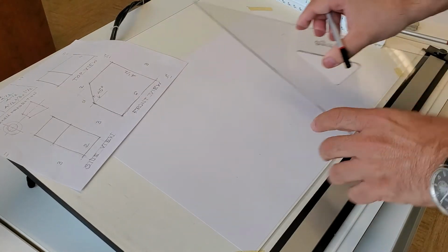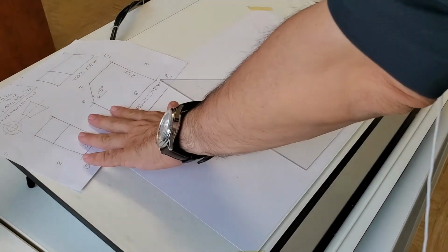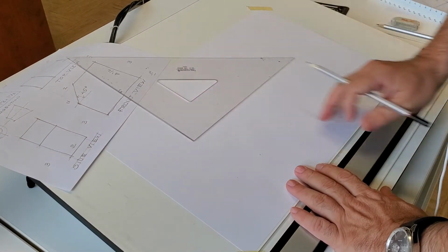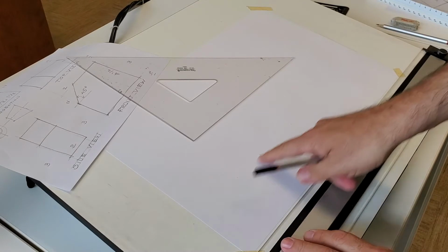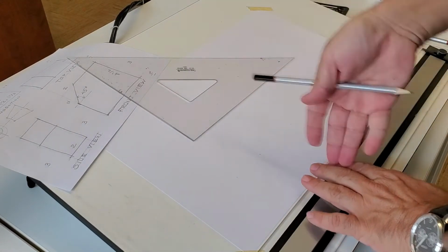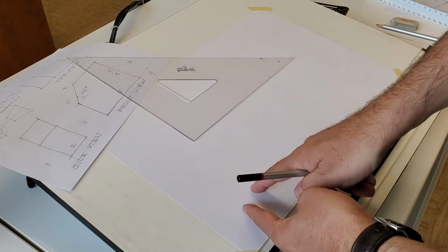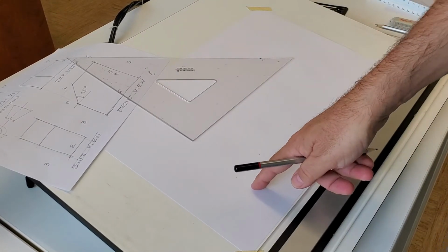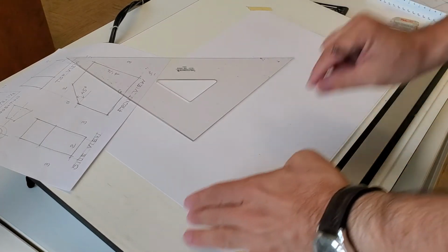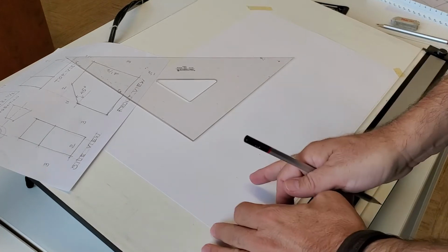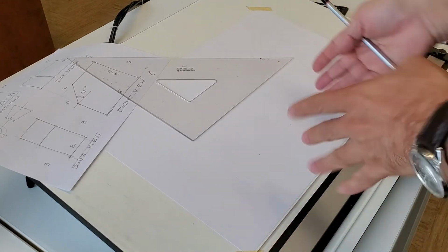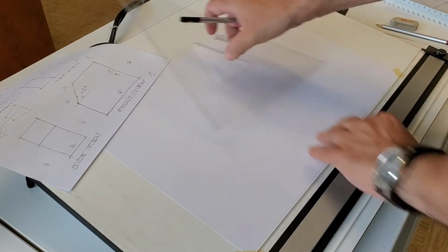Okay, so one thing is important, that you always work in series. It means that when you are doing a task, finish all of it as much as you can. Here I put all the dimensions, I mark them, and then I will draw one by one. I will not measure and then draw, and measure and then draw, because you have to put the ruler, measure, put it aside, take a set square, make a vertical line. It takes too much time. Okay, so here we go.